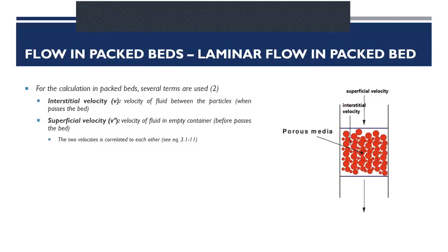Now we go to the next slide. There are still several terms that we use to calculate packed beds. Again, there is the interstitial velocity, or V, and we also have the superficial velocity, or V prime. The interstitial velocity, V, is the velocity of the fluid between the particles when it passes through the bed, just like in this graph.